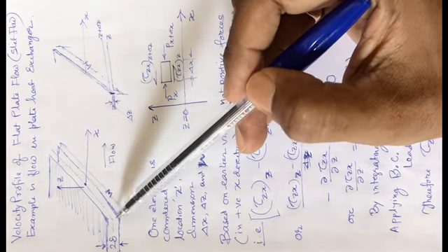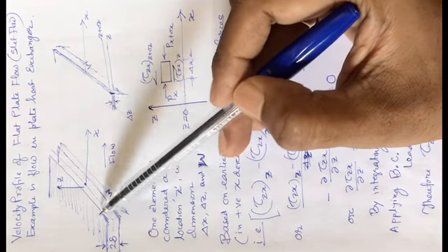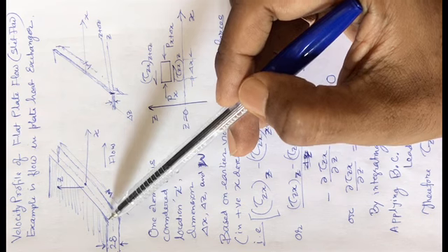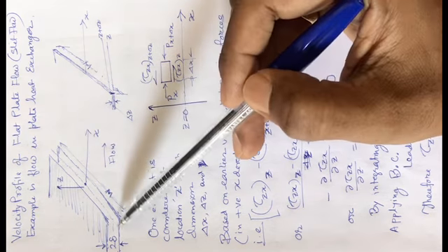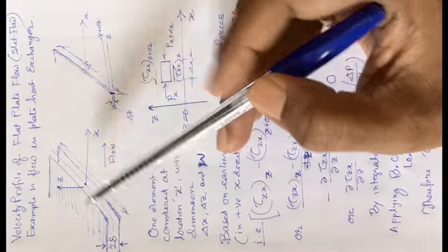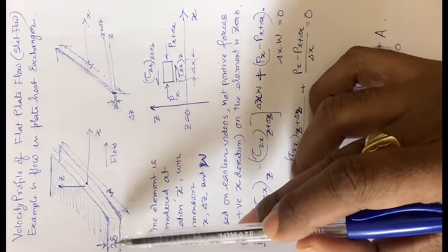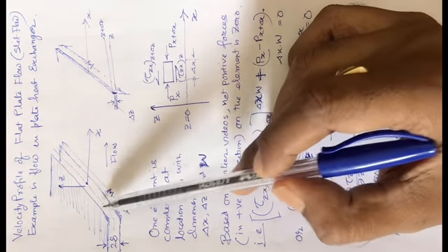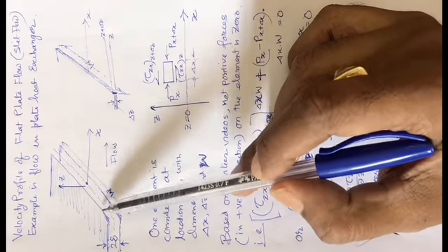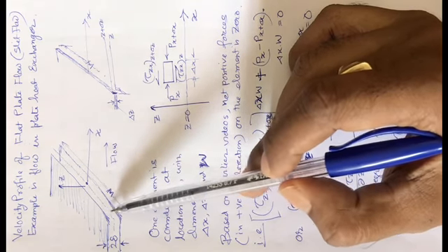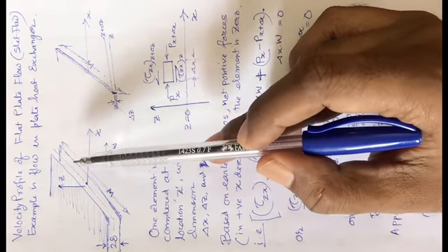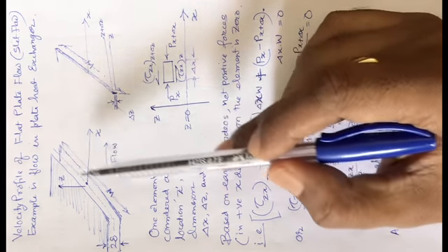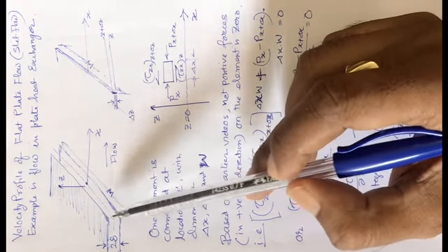So what happens is that the gap between two plates is quite small, whereas the width is quite large. Fluid is flowing through this gap from left to right. This is one plate and this is another plate. One plate is placed above another with some spacing provision for maintaining the spacing, or some spacer. In a plate heat exchanger, you know that gaskets are used. So with some support, that gap is maintained.